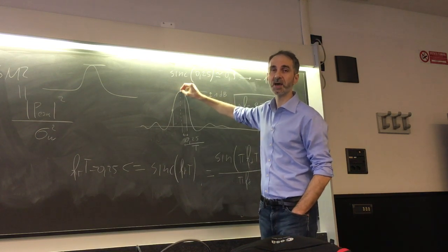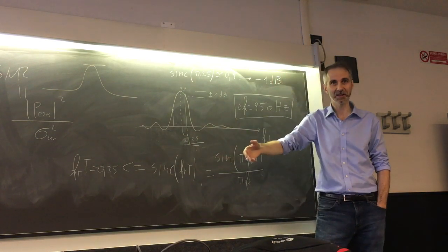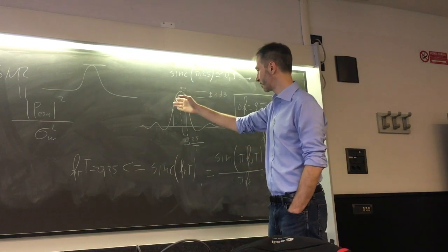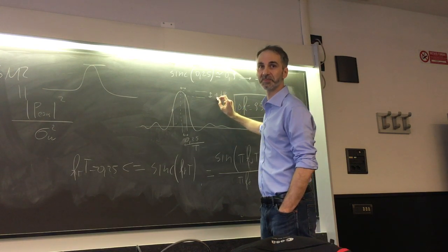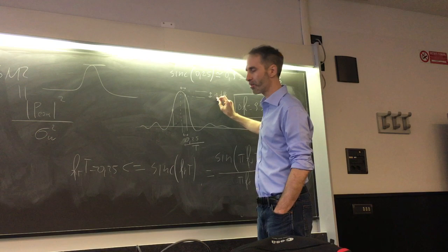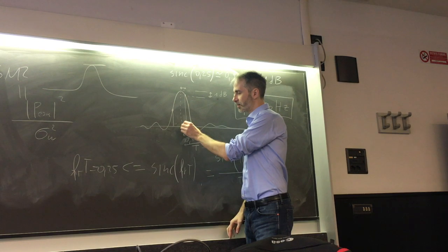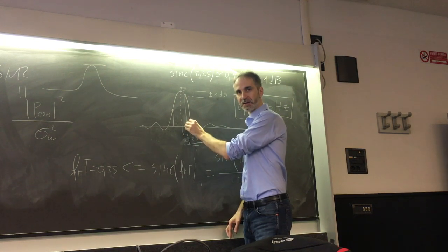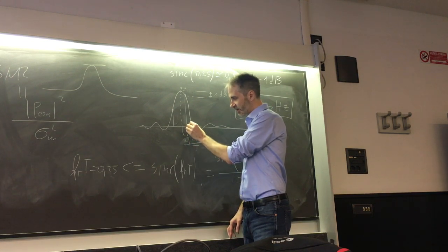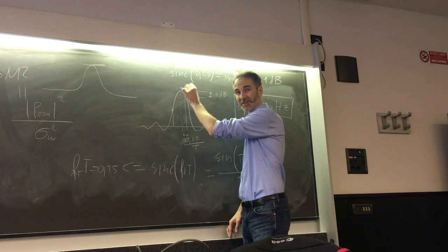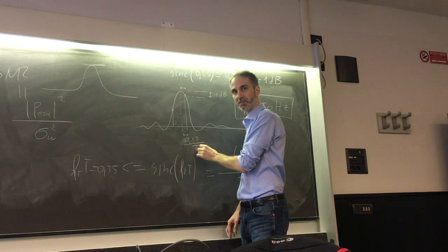You don't want to use an infinite number of frequencies, because you want to do other things in your life, and so you just divide this, and you don't want to lose more than 1 dB. So not to lose more than 1 dB means that the frequencies that you are using can differ from the real Doppler frequency by no more than 0.25 divided by t.